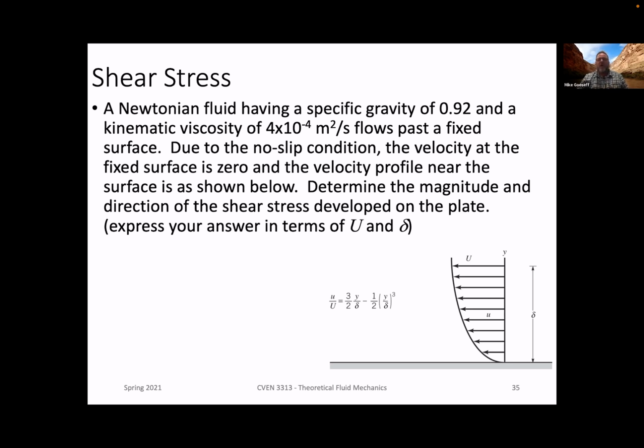Newtonian fluids are ones that will deform more when we provide more shear stress at the surface. So, for example, honey is not a bad one. Water, oil. When we get to things like peanut butter, you now have a certain shear stress you have to overcome before something moves, for example. There might be some other ones we could think of, but in any event, sometimes we qualify this as saying a Newtonian fluid, meaning that it should move as soon as we apply some stress.